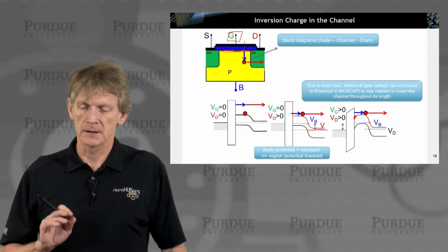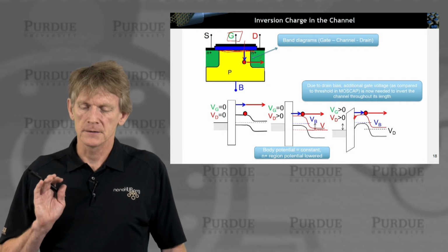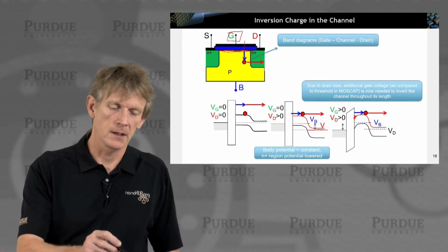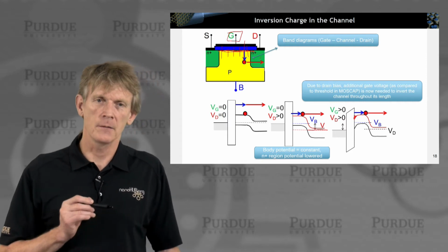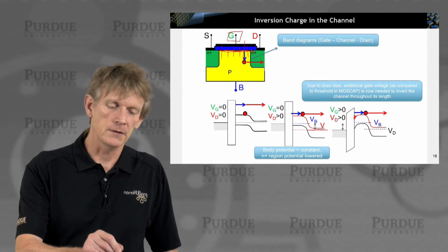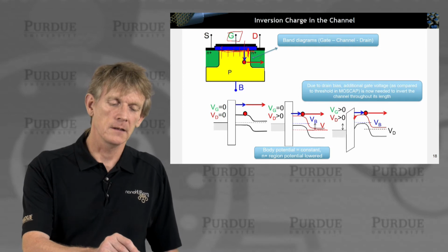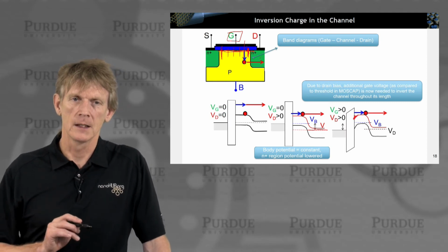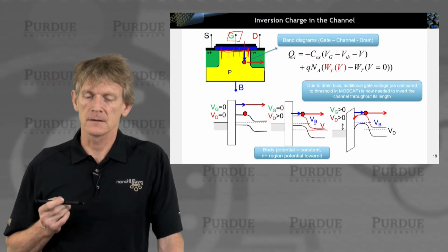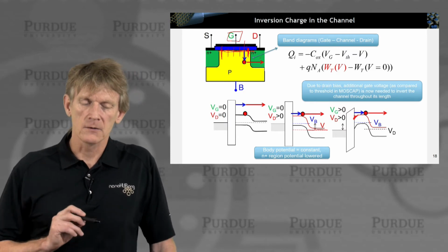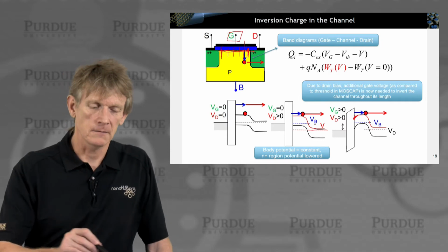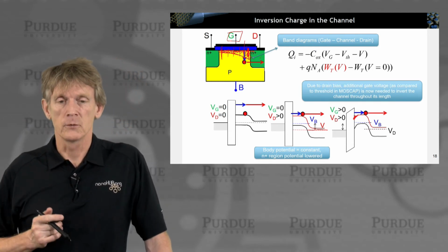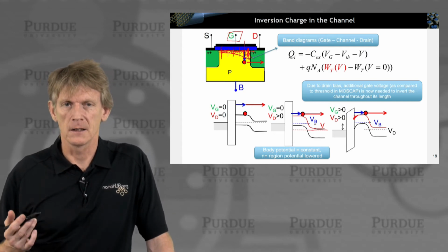So the drain bias provides an additional voltage, and the gate voltage is needed to really create an additional channel. Okay, and that has to happen throughout the channel. It has to happen here, here, here, and here, and here. And you can imagine that the effect of the drain voltage is more dominant here towards the drain end than on the source end. Okay, so you have a spatial modulation of this notch and the distribution of Fermi levels in the channel. Okay, so you can imagine that the depletion region that you have in the system is now spatially varying. Okay, so you could argue that there is a region that is getting thicker and thicker in which you deplete the charges, or you make the channel thicker and thicker.